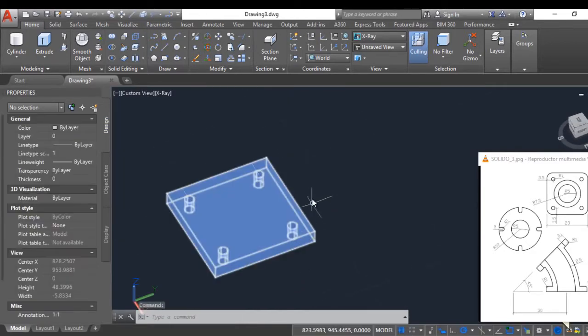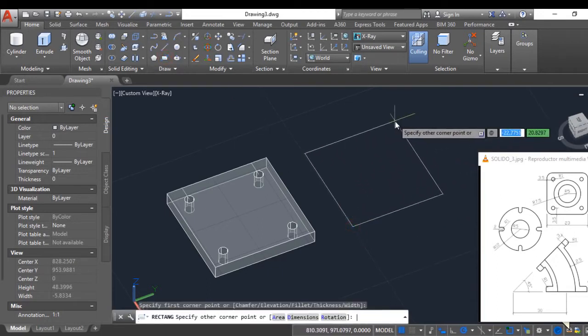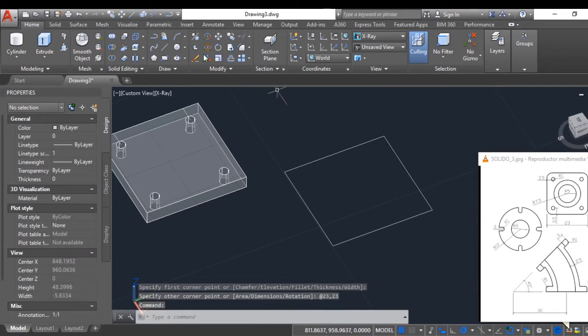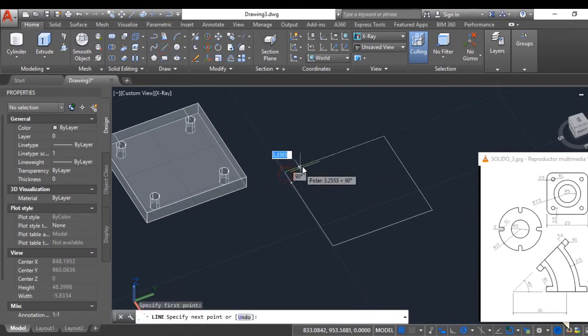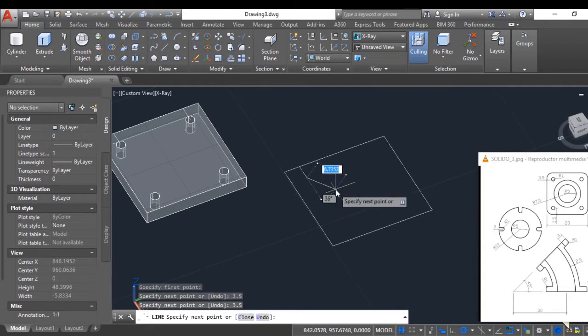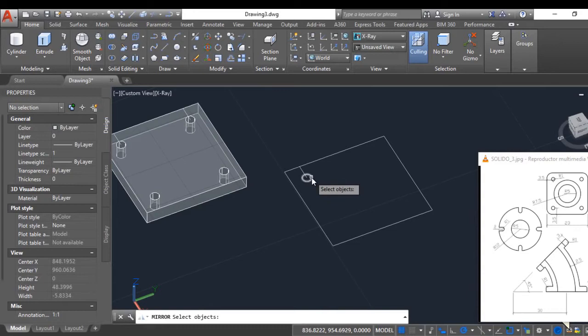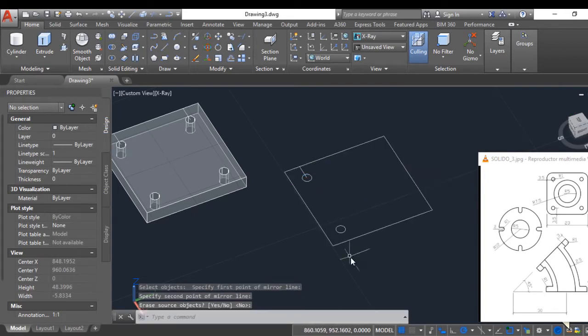Right. I'm going to show you another way to do it, with a polyline and with press pull. Then quickly, we can also do this at 23 by 23. Here it is. Now, I'm going to make a help line over here. It is 3.5 and 3.5, always waiting for the ray, because I have polar tracking activated. So, here I make a circle of radius 1 and I just use mirror. I run the mirror tool, select the circle, and click here and in the middle points, so that it is copied in parallel.